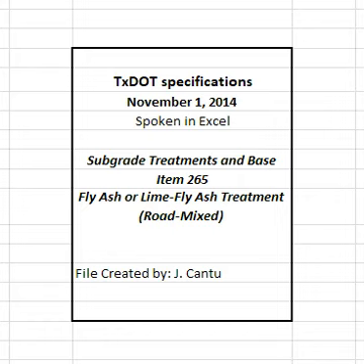4.3.2 Mixing of lime. Begin mixing within 6 hours of lime application. Thoroughly mix the material and lime using approved equipment. When treating subgrade, bring the moisture content above the optimum moisture content to ensure adequate chemical reaction of the lime and subgrade materials. Allow the mixture to mellow for 1 to 4 days as directed. When pebble-grade quicklime is used, allow the mixture to mellow for 2 to 4 days as directed. Sprinkle the treated materials during the mixing and mellowing operation, as directed, to achieve adequate hydration and proper moisture content.